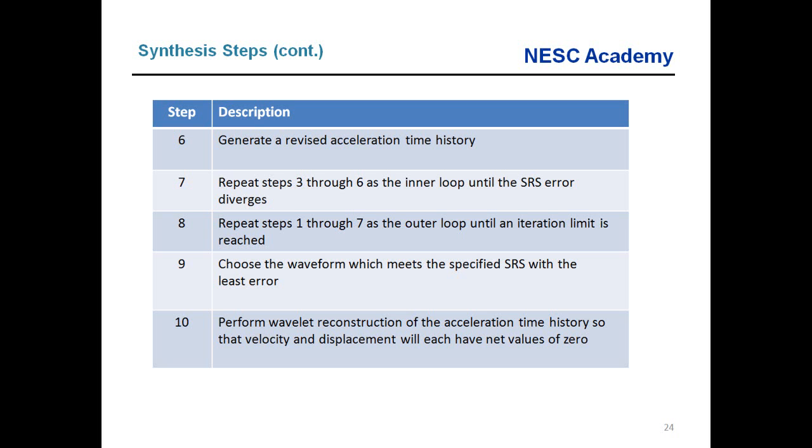So think to yourself, you've got two points on that component, and each of those two points has these very high absolute displacements due to that ski slope effect. So you might think to yourself, okay, well, they both have the same ski slope effect, so if I subtract the absolute displacement at point A from the absolute displacement at point B, that will give me the correct relative displacement, and I don't even need to worry that there was a ski slope effect. That just all comes out in the wash. So what's the problem? Well, here I'll tell you what the problem is. That absolute displacement due to ski slope may be up to 2,000 inches.